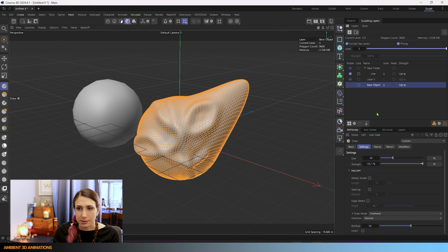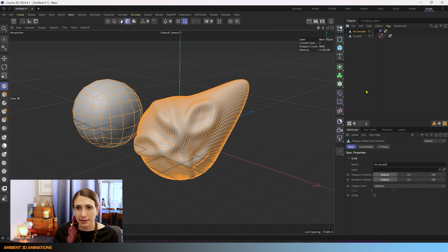So what happens in the case where we click on this and instead of having our smoothness set to 100%, what if we have our smoothness set to 0? Now the interesting thing about the smoothness setting is that you can only change it the first time you hit the subdivide. After you hit the subdivide, you can no longer adjust this. You can't change your mind about how smooth you wanted it to be. So you need to set this right the first time.